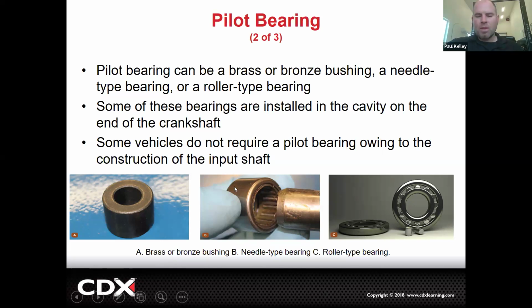But personally, I think the bearing's a little bit of a better option, as long as the bearing's well made, because you actually have rollers. The bearing basically should be able to withstand more forces and not wear, right? There should be almost no friction here, whereas this is inevitably going to have some friction. Cool. So you have different types of pilot bearings there.